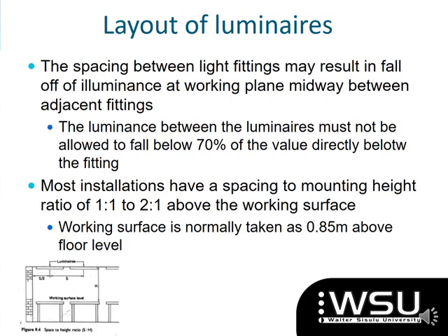So now that you've got the 15 light fittings that you are going to spread out in this room, we need to determine how we go about installing them, like what distance from each other, or how we go about doing the entire installation or design of installation. So here we're going to learn about what we call the spacing to mounting height ratio. So it's the space between your lights compared to the height of where these lights are mounted above your surface point or your working surface, as we call it.